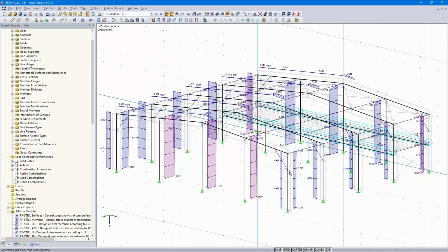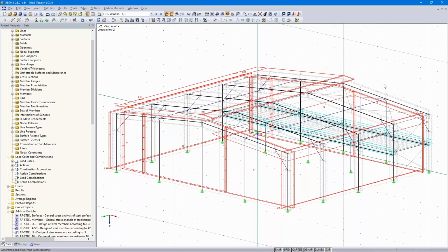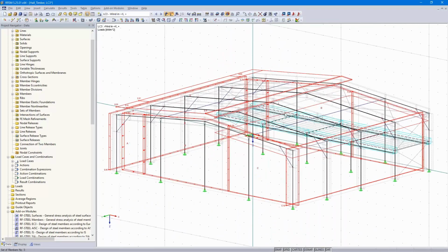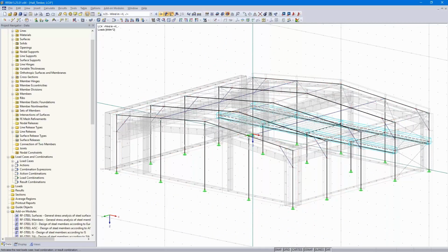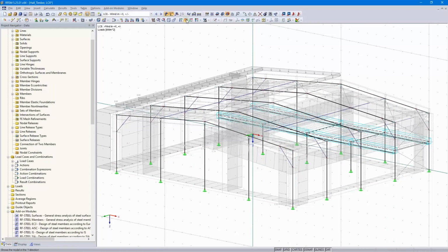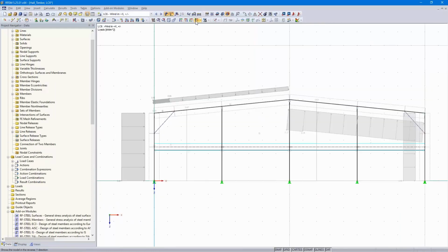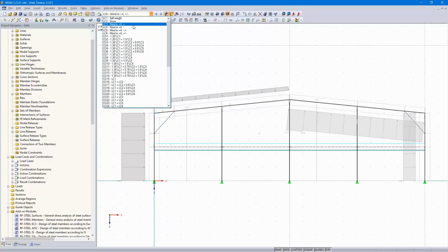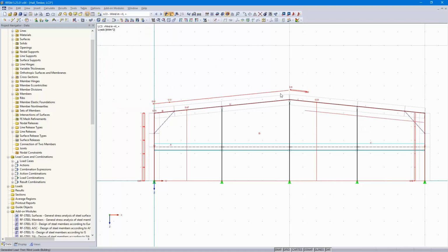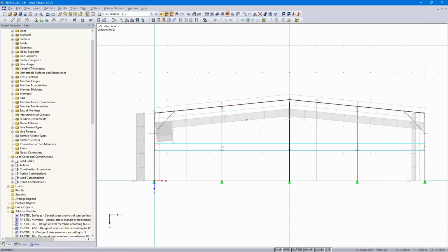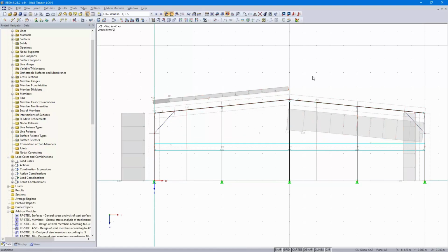And all loads are created automatically. I can also display the surface loads. Okay, 4 wind load cases have been created. So I can show you. The combinations are created automatically. So wind load case 3. The load on the walls is the same for all 4 wind load cases, but here wind load case 3, pressure and pressure, 4, suction, suction, suction and pressure, and pressure and suction.